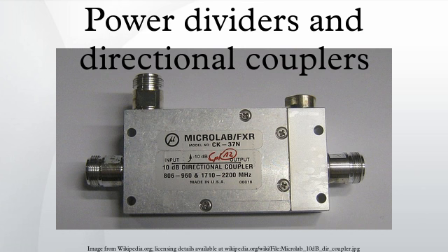For a passive lossless directional coupler, we must in addition have, since the power entering the input port must all leave by one of the other two ports. Insertion loss is related to the transmission term. Coupling factor is related to the coupling term. Non-zero main diagonal entries are related to return loss, and non-zero anti-diagonal entries are related to isolation by similar expressions. Some authors define the port numbers with ports 3 and 4 interchanged. This results in a scattering matrix that is no longer all zeros on the anti-diagonal.